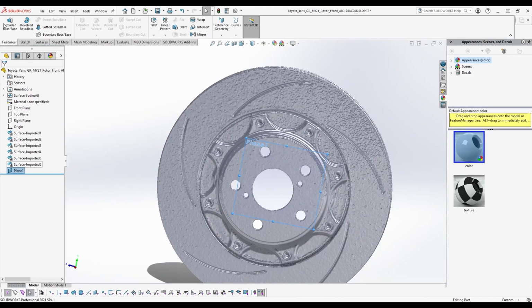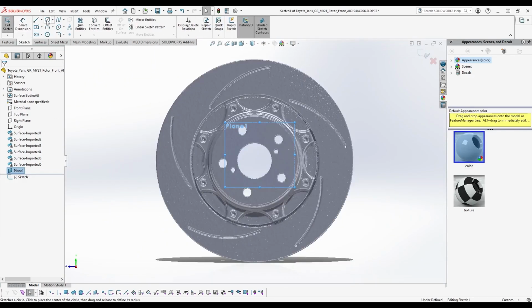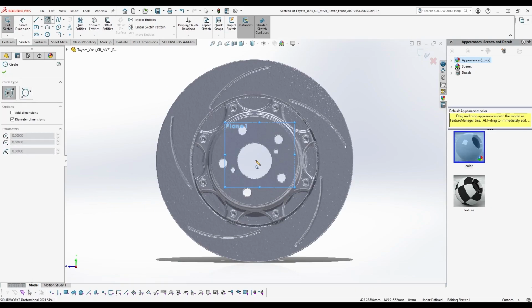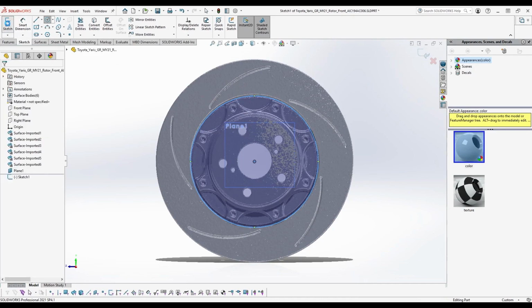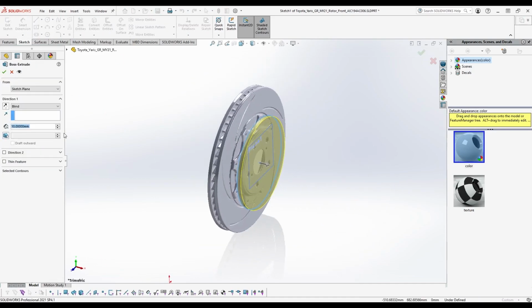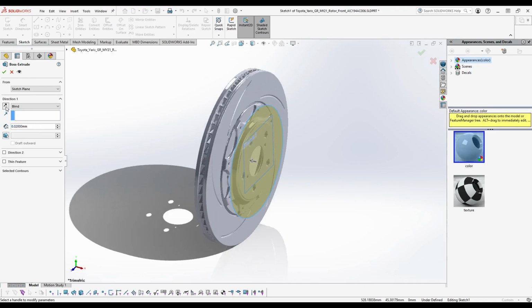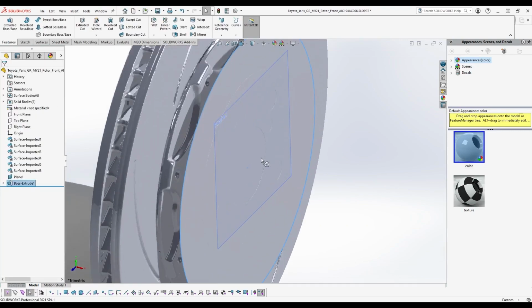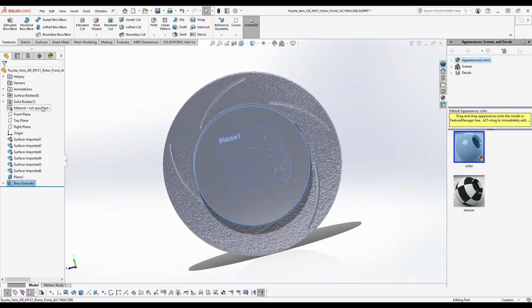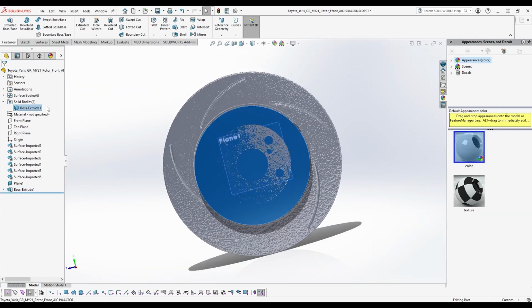And if I wanted to check that, there's probably better ways to do it, but I can just chuck a quick sketch on there, and I'll extrude it to the tune of, say, 0.02 millimeters, and see. And again, this is where giving stuff an appearance can really help.